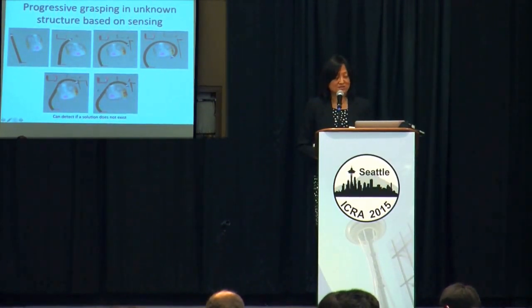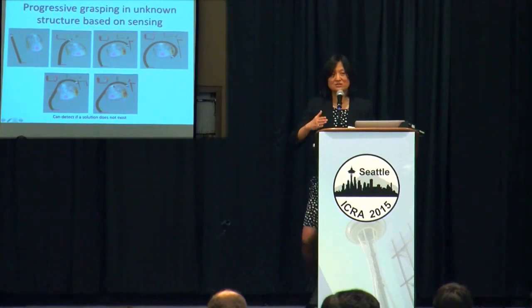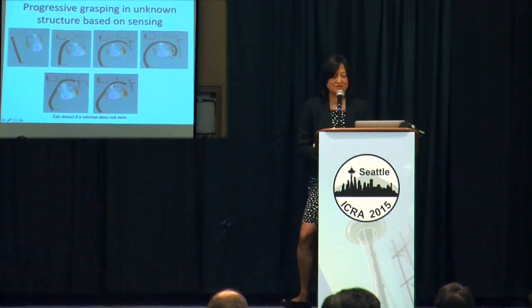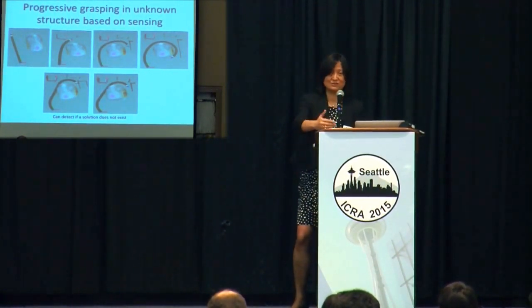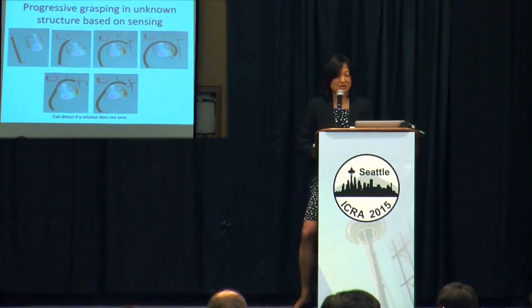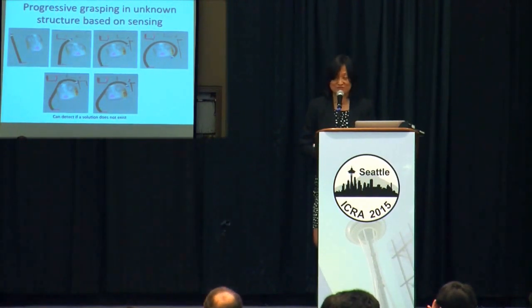And in this case, the gap is wide enough for the same area to be grasped, but in order to make the robot wrap around this object, the top space is too narrow. So we have to consider a concatenation of these so-called gap constraints simultaneously as we start discovering the structure and object, to decide if a solution exists. If a solution exists, we can always find it.